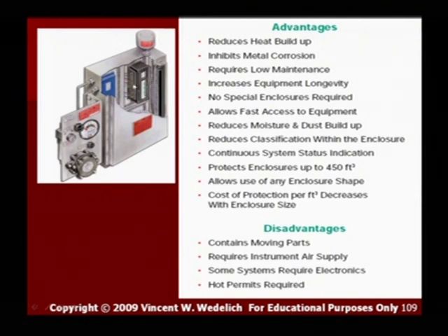And now here we have a regular PLC or different devices that are, in this case, you can see this enclosure right here is actually a NEMA 7 enclosure. We'll talk about that. So more than likely, this is a Y purge or even an X purge. Anyway, basically what happens is you flood the inside of this enclosure with instrument air or an inert gas from a safe area, and you prevent the gas from the atmosphere around it from getting inside the box.